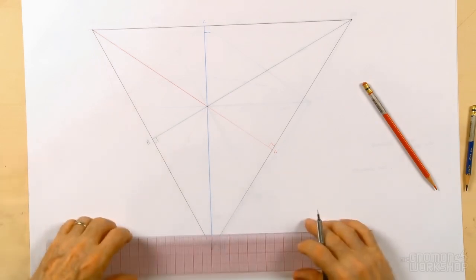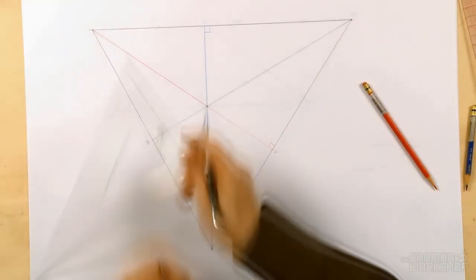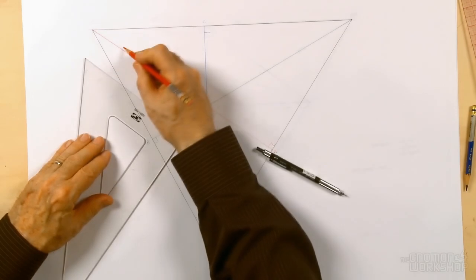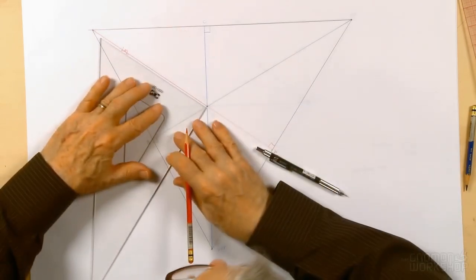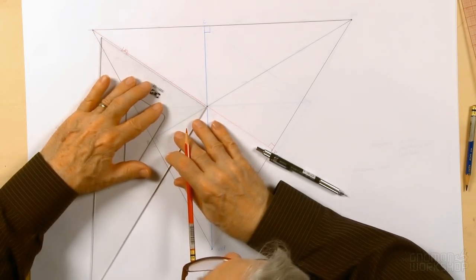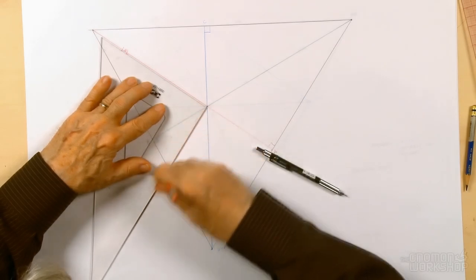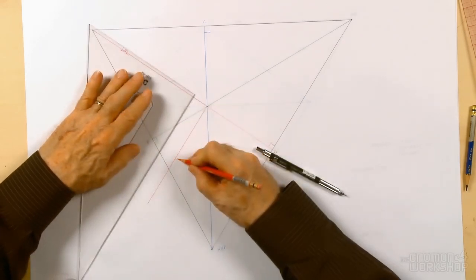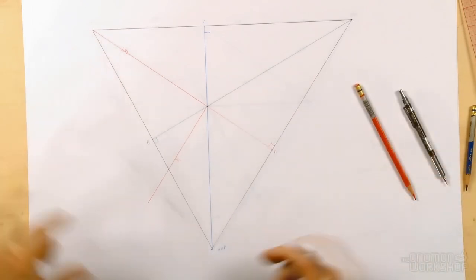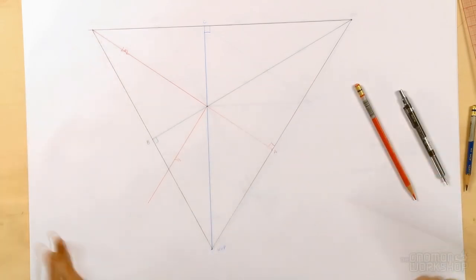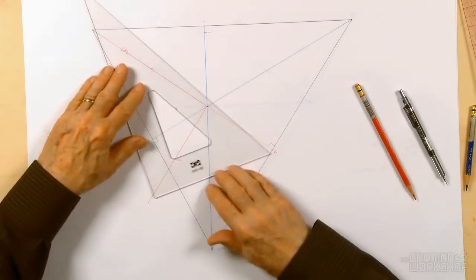So what I'm going to do next is come relative to this red left reference line. By the way, let's identify this as a left reference line, like we had in 2-point perspective. In this case, this will be the left reference line. And this line coming out from the left reference line like this is what we call a distance line. I'm going to put DL on that. It's a distance line. Now, we're setting this up in a way that we're just going to accept the distance that works out here. There is a way of plotting a distance, but right now, let's just do this.